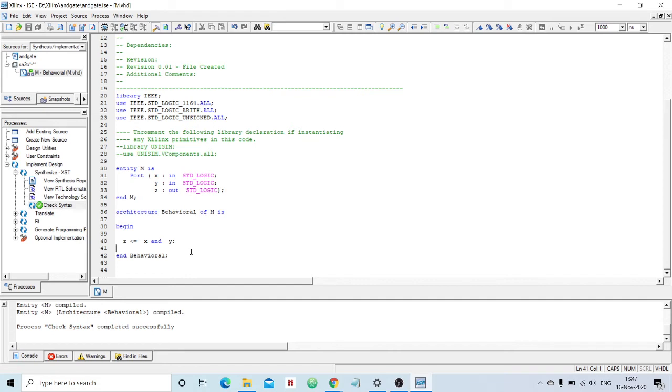Clear? After this, if I take an example of C programming, after compiling the C code, what you people will do is execution, right? Here instead of execution we will call it simulation. Now we have completed 50% of our work. For simulation, can you see a sources for drop down box or selection box here? Initially it will be on synthesis. After synthesis, after compilation, you have to go for simulation. And remember, since we are using a behavioral model, we have to choose behavioral simulation.